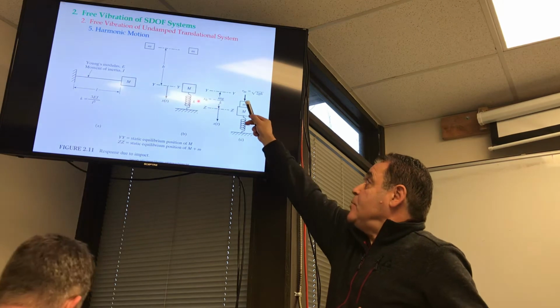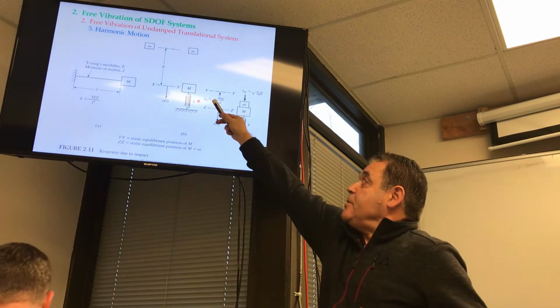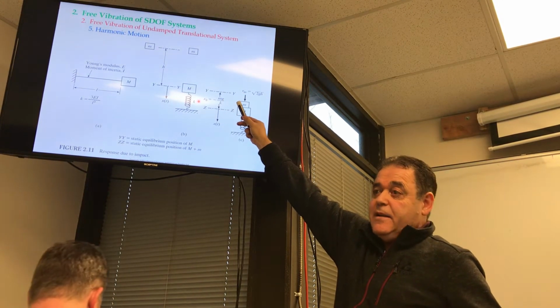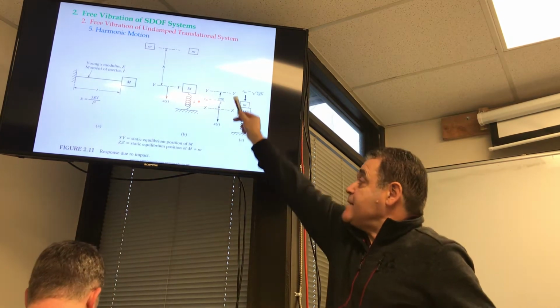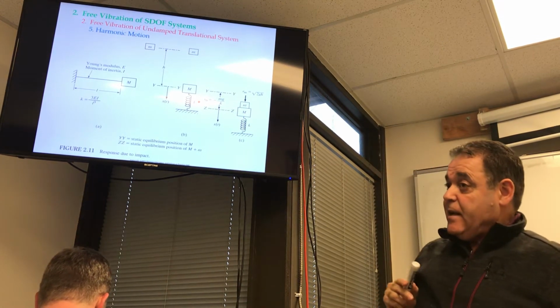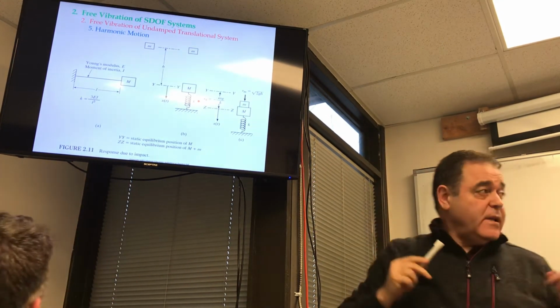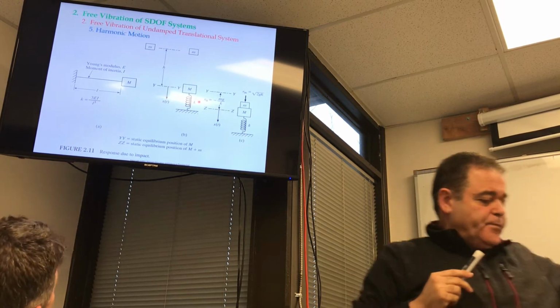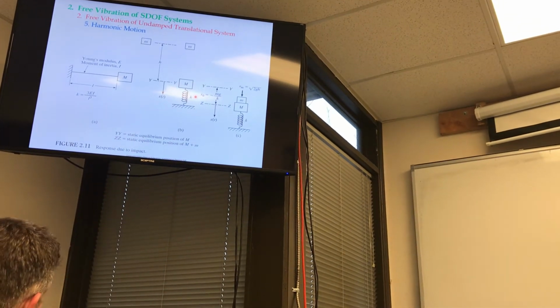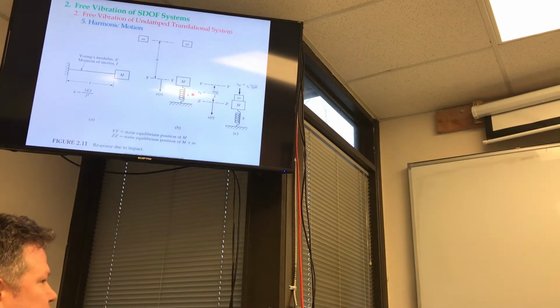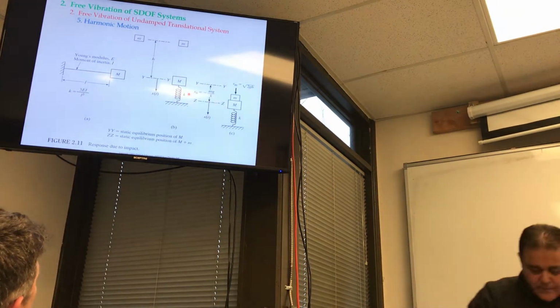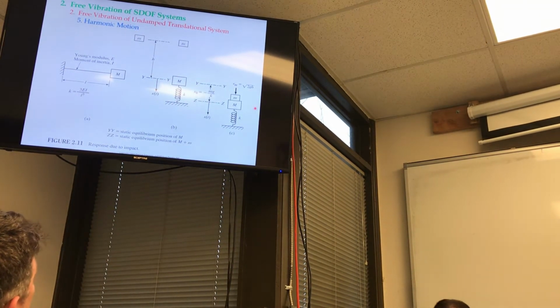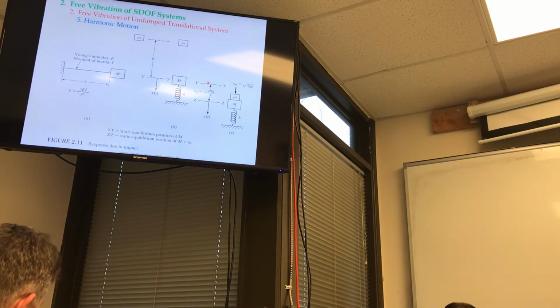So at time t equal to 0, my mass was there because that's where impact occurred. That means the location was x naught equals minus mg over k, and the v common will be the initial velocity, the velocity that is used to compute this equation. Okay, so I'll let you look at that one and this one.